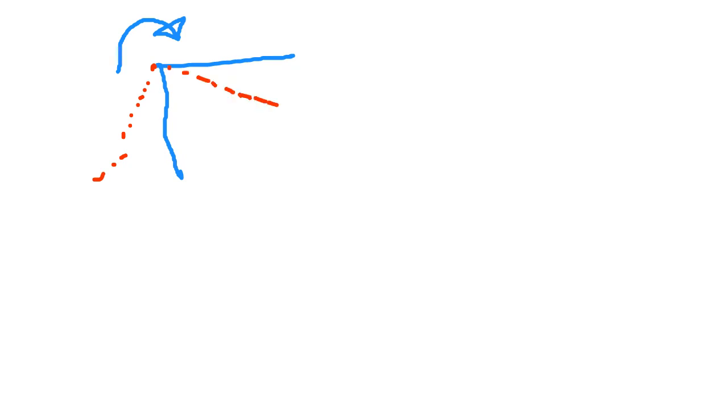That is the beauty of a rigid joint. If the joint is rigidly connected, both will have the same rotation. So if it is 30°, this will also be 30°.